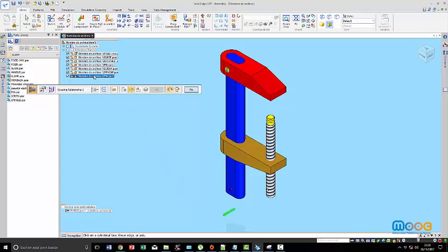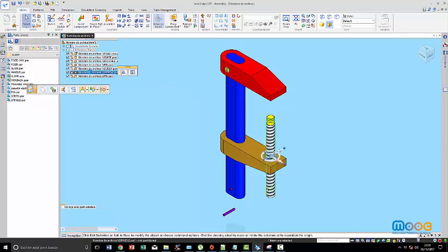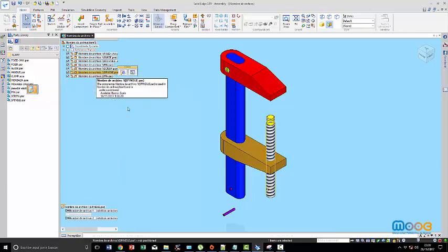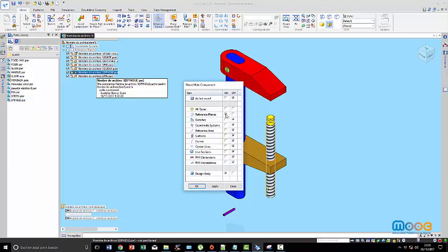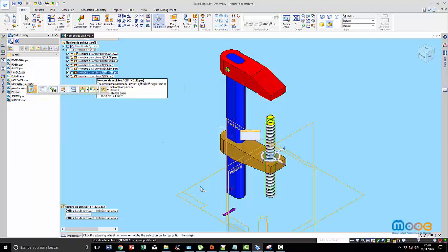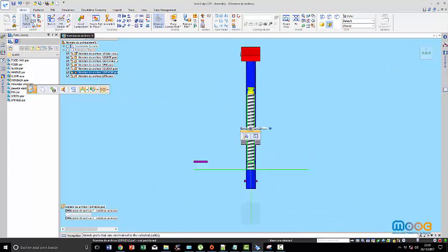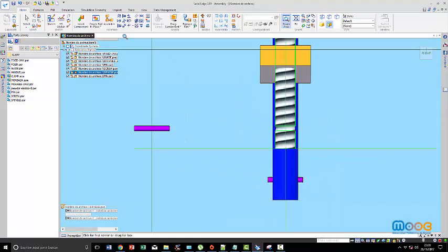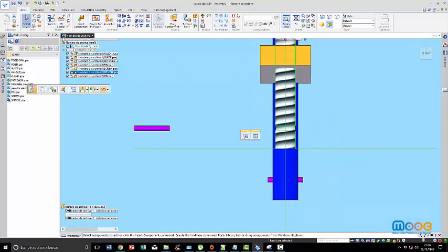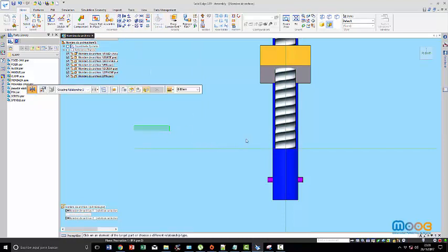As I have done before, I'm going to activate the reference plane for the spindle because I want to have it perfectly centered, because the draft will be better drawn and I don't want it to move when I include the motors. So now I state a relationship mate faces between the face of the pin and the reference plane, remember, of the spindle.